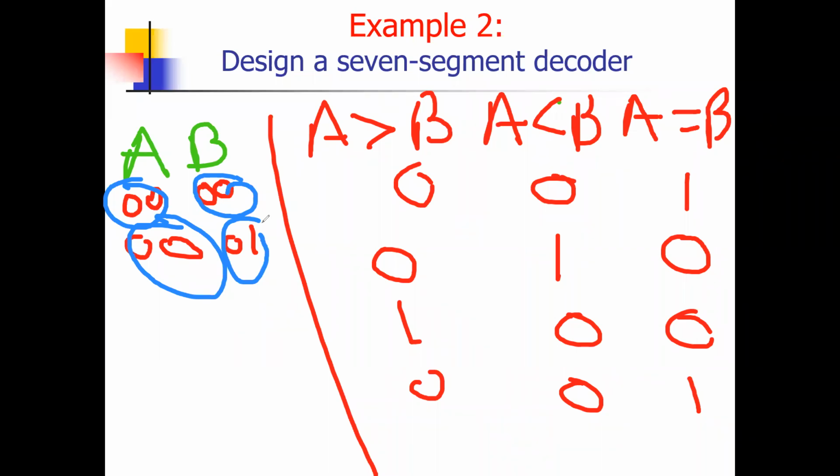ABCD you cannot do. If we have ABC, then with 1 bit, 8 combinations will be there. Then you can compare: 1-bit, 3 variables, you can compare. But if you have 2 bits, there will be a 6 variable K map. You cannot do that using K map, because I didn't teach you. I teach you only 2 variable, 3 variable, and 4 variable.